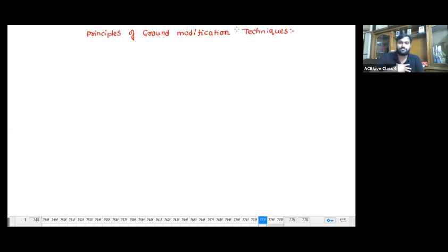So now I am an engineer and I know everything. I know the soil has low bearing capacity, and I know the structure will be very heavily loaded. And I know that my client wants to get it done at less cost. So I cannot go for a shallow foundation as the bearing capacity is very low. I cannot go for a deep foundation as the cost required for the project is very high. Now, what option do I have? The other option is, okay, the soil is loose. Let us try to improve the strength of the soil. Let us try to improve the stability of the soil.